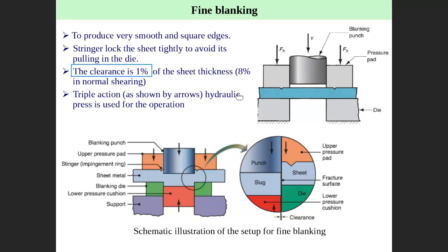I understand, but I would like to have no distortion. Make it a fine blank. There are none of these regions that we described, rollover, fracture and zone. I need a fine blank with a very straight edge. Can you see? With a straight edge.